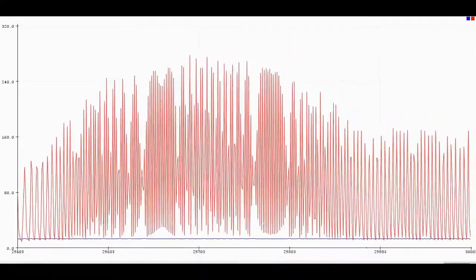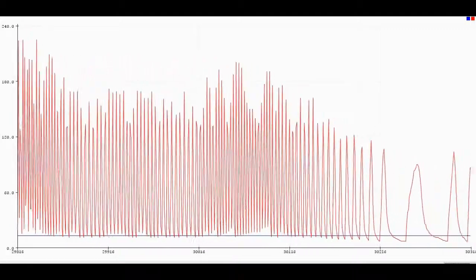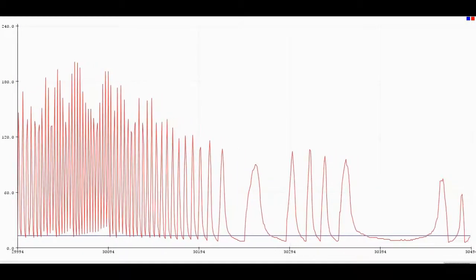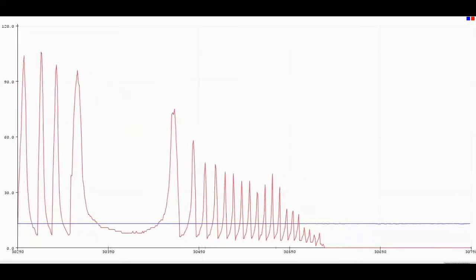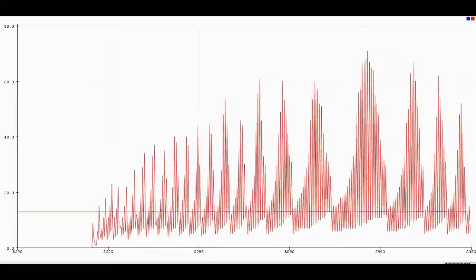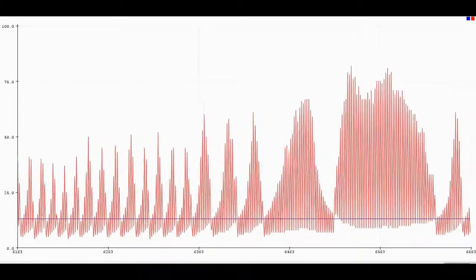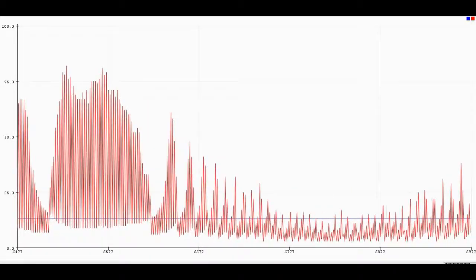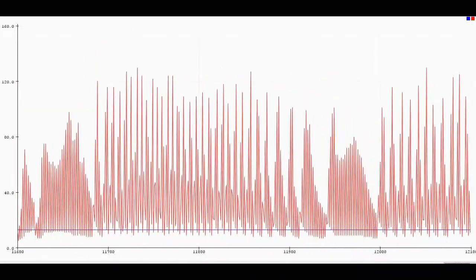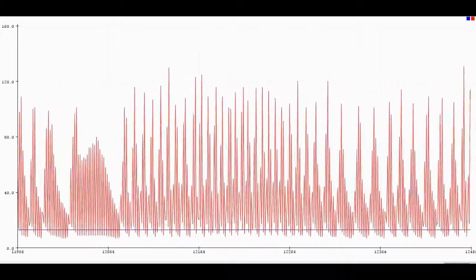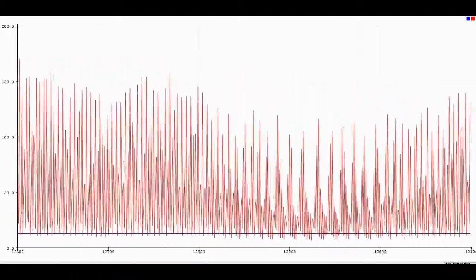Here's a closer look at the output of the amplifier. First at a sampling rate of 20 milliseconds, and you can see how it's interacting with the frequency of the generator's output, the current pulses. And if we increase it, this is 10 milliseconds, and you can clearly see the problem here is that the current comes as pulses from 0 to their peak value, and again at 5 milliseconds it becomes very obvious. You can almost see the individual current spikes.